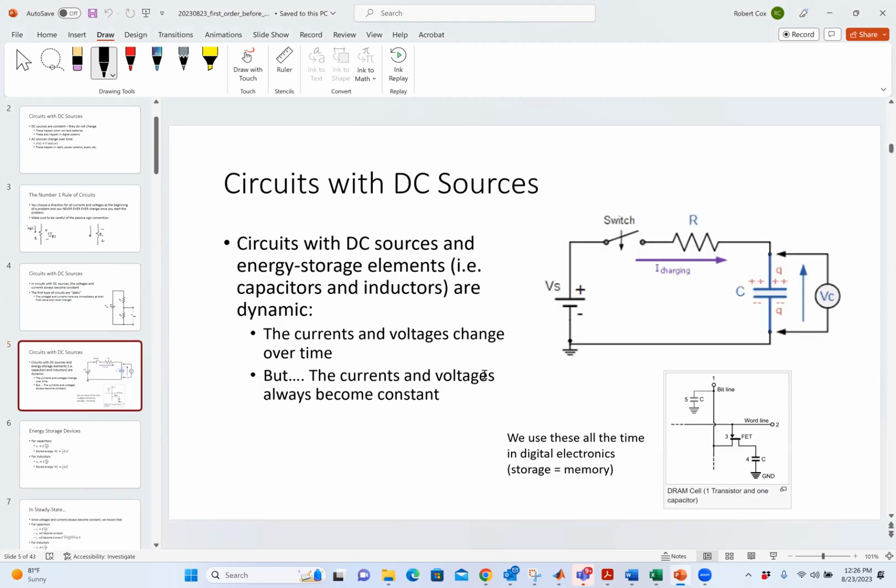example typically is an RC circuit where I have a resistor and a capacitor. And you guys know that what should happen is when I close that switch, the capacitor is going to charge up. And eventually, if this voltage source over here is a DC voltage source, if that's 5 volts, what's going to happen to the capacitor over time? It's going to go to 5 volts, right?